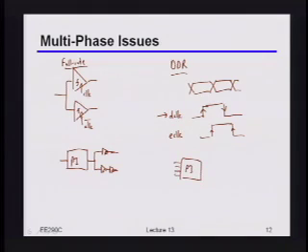I've got 4 phase inputs into that phase interpolator, giving me 1 output. Well, I could indeed just copy the phase interpolator, take those same 4 phase inputs, but just rotate the code by 90 degrees, right?